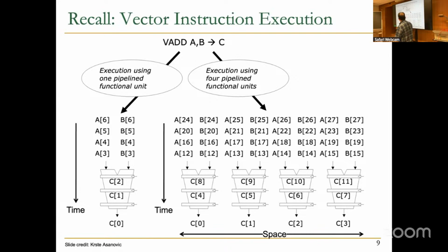processor and vector processor. Here we have an example of a vector processor where you have a processing element, and then you have different elements of your arrays, and you're feeding them to your pipeline. But then what you can do is multiply this, and you have different instances of these processing elements, placed in space. And then you can categorize your data and map the elements to each of these processing elements. And with that, you can have a kind of array processor, where each of them is a vector processor. And with that, you can combine these two paradigms nicely together.